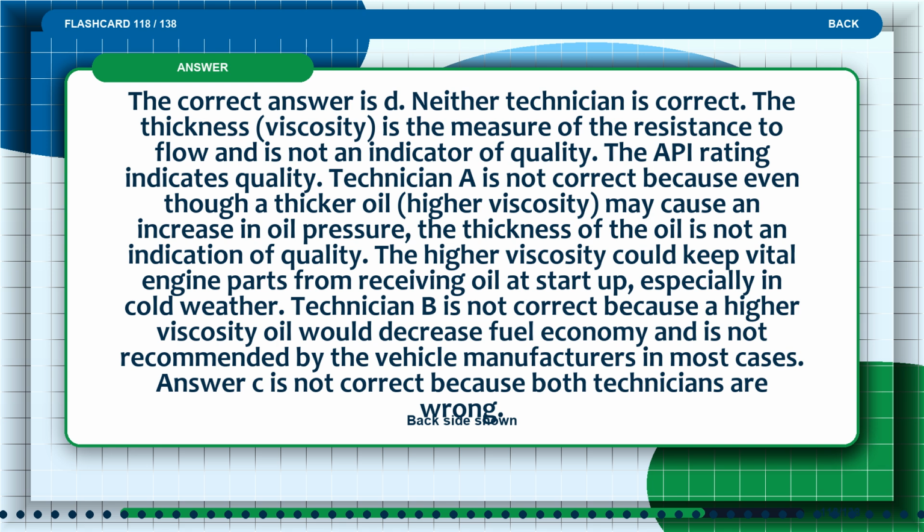Technician A is not correct because even though a thicker oil, higher viscosity, may cause an increase in oil pressure, the thickness of the oil is not an indication of quality. The higher viscosity could keep vital engine parts from receiving oil at start-up, especially in cold weather.